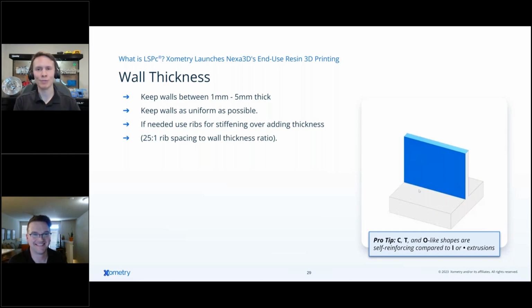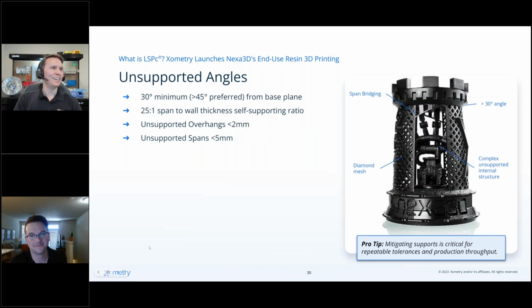You're introducing risk into that decision. So by keeping within these wall thickness guidelines, you're going to have a much more consistent part, both on the output as well as expectations. And also, you may not get a call from our case management team when we see a DFM flag on it, because we do check your designs afterwards and make sure things print smoothly.